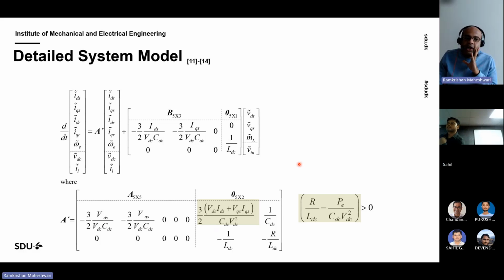So not good. What I did in our lab, I had a DC motor coupled, and then I changed the resistance load on the DC motor. Now, if I change the resistance, the DC motor has its own dynamics, so it will take some time to convert that into speed and torque, and it was a slow process. With that, it works. That's what I did in the lab. But not a sharp change in the torque, and even where I had a sharp change in the speed reference, the speed was ramped down. Okay.